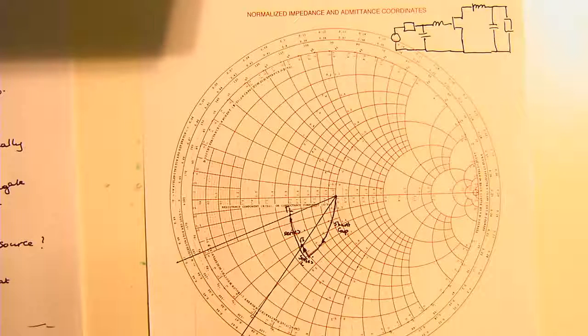For the given biasing conditions and for the noise characteristics of that transistor, this is the configuration of input and output matching networks which will give you the highest gain and the minimum noise. You can't do any better. Okay?